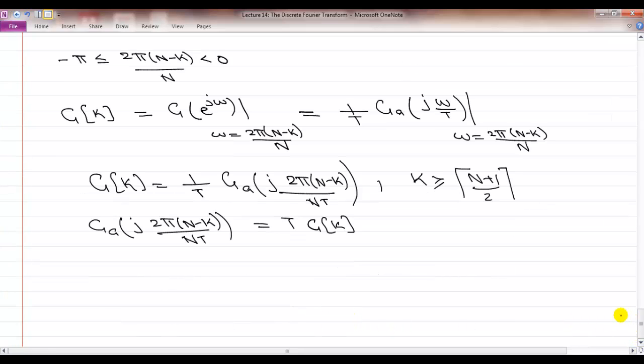So the way spectral analysis works is you compute your DFT coefficients, and you do your FFT shift so that the DFT coefficients that correspond to omega equal to pi to 2 pi go to minus pi to 0. And then you simply relabel the x-axis. You know the relationship between the different coefficients and their continuous time frequencies, and you also scale the amplitude.